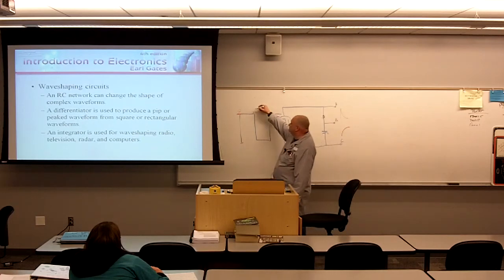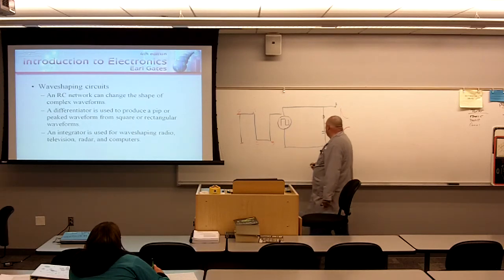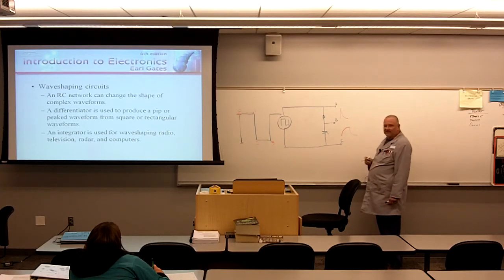So, from point number 1 to point number 2, what happens at my square wave? It goes from 100% to 0. And then it holds. What condition is this? Basically off between time 2 and time 3. So, what's the capacitor going to do? It's going to discharge, and it's going to look like a capacitive discharge.